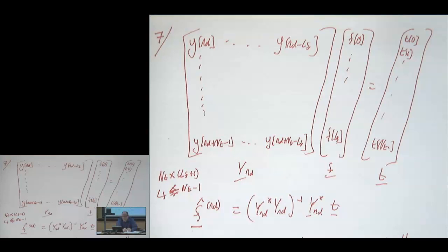I was just thinking about, as it relates to machine learning, basically doing a very similar thing. Right. I mean, your training data is really important. Here it's a little bit different. The way to see the value of the training data is if we try to estimate the channel. There's a covariance matrix that we essentially empirically estimate that consists of the training that we use for the channel estimate. And that matrix should ideally be close to an identity matrix, which means you should use training sequences that are uncorrelated in some sense.